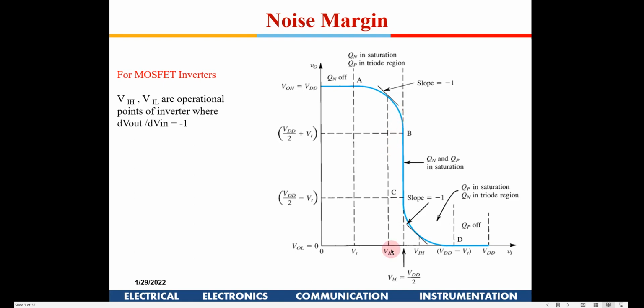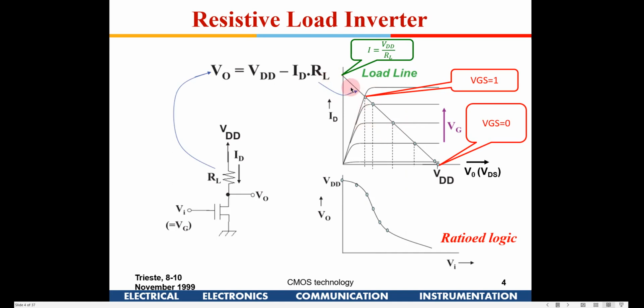Okay, so obviously when you are giving VIL, the Vout won't be VDD. There will be a small drop, but still we assume that. But even that little bit of drop won't affect the next stage. It will still be considered as a 1, because it is way beyond the threshold voltage of the inverter itself. So that is the reason that voltage was fixed like that. Okay. Now, I have a tendency to go fast. So if you keep posting your doubts out here, that will normalize my speed.